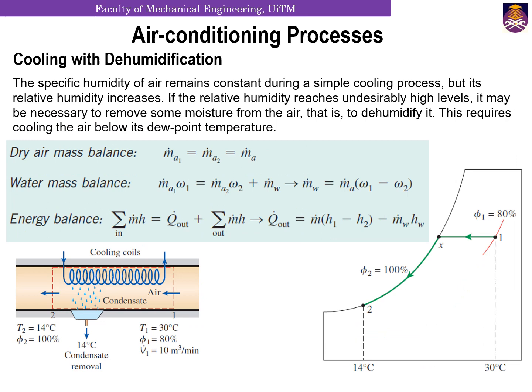We also have the next part, which is cooling with dehumidification. In cooling with dehumidification, as you can see here, we are reducing the temperature. So when you reduce the temperature, point 1 moves towards the left of the psychrometric chart until your relative humidity becomes 100%, or the air reaches such high humidity that it becomes saturated. So another meaning for the saturated level is humidity at 100%.